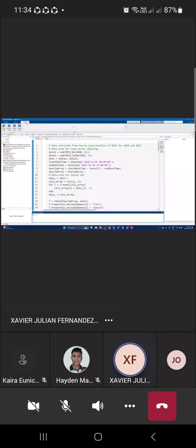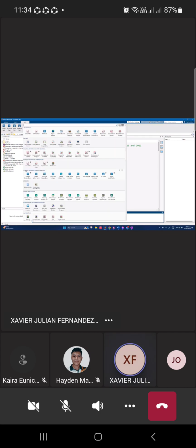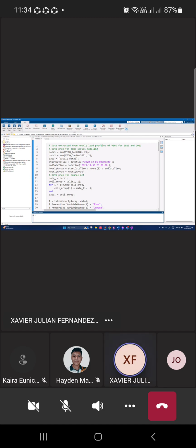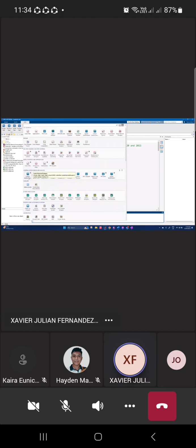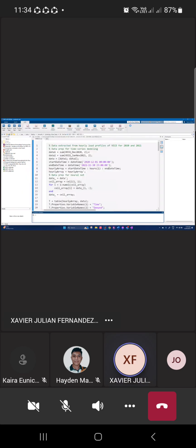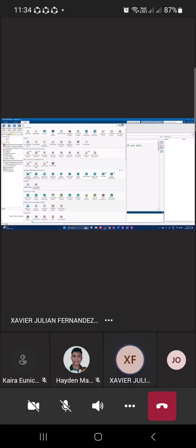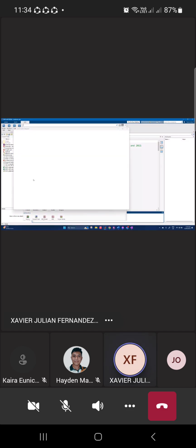Apps, and then you click this drop down button, you find this control system design and analysis. Okay? And you look for the control system designer. That's usually the first one. Here you can design SISO controllers, because actually in the control system designer, you design the controller there. Mainly. Okay?